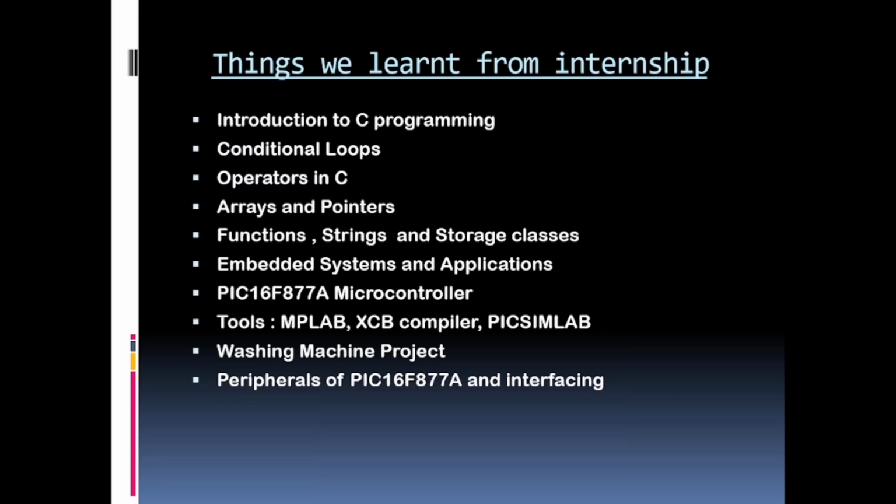One of the major highlights was learning about PIC16F877A, an 8-bit microcontroller that we used in our final project. To develop our project, we used industry standard tools: MPLAB for writing and managing our code, XC8 compiler for compiling C code into machine language, and PICSIMLAB to test and simulate our design.